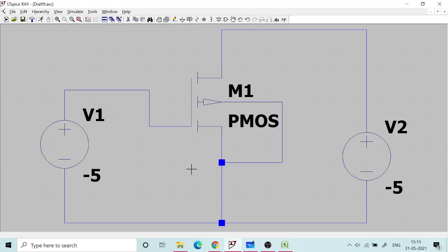So this is a difference between Nmos and Pmos. In a Pmos transistor, the bulk region, the semiconductor substrate, is made up of N-type material, and we need to apply a negative voltage to repel those electrons and create the depletion region initially.